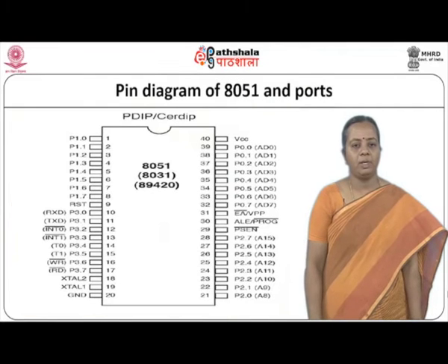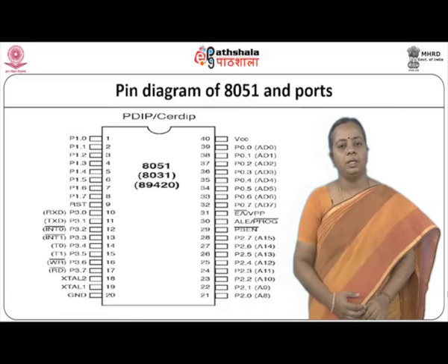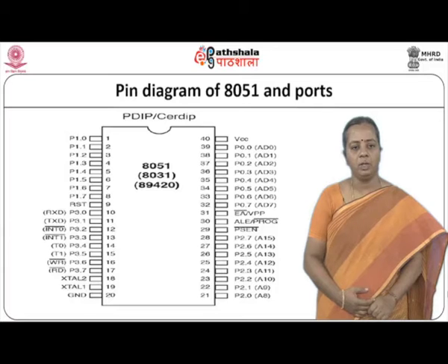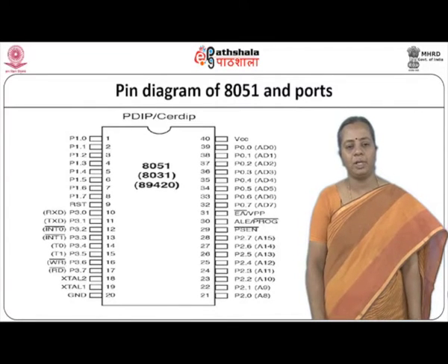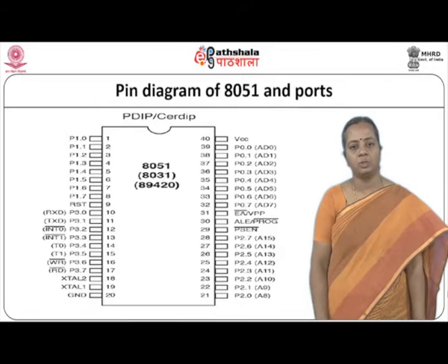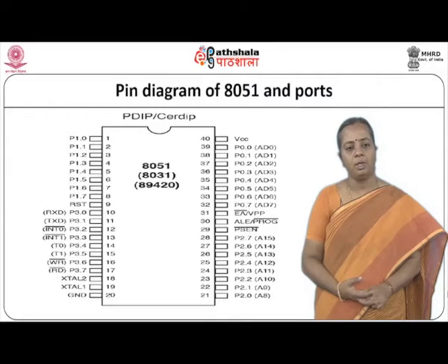When you are looking at the 8051 microcontroller, we have a 40 pin chip. In that 40 pin chip, the 40th pin and the 20th pin are VCC and ground, and we have 4 parallel ports. 2 of the ports will be used for sending your address as well as your data, receiving or sending data to memories or different input output devices, and the other 2 can be used for interfacing with input output devices. One port is special: it can be used for input output as well as for some special purpose.